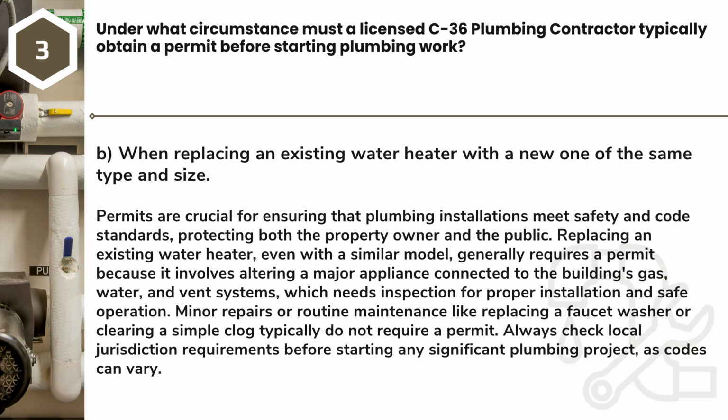Answer: B. When replacing an existing water heater with a new one of the same type and size. Permits are crucial for ensuring that plumbing installations meet safety and code standards, protecting both the property owner and the public. Replacing an existing water heater, even with a similar model, generally requires a permit because it involves altering a major appliance connected to the building's gas, water, and vent systems, which needs inspection for proper installation and safe operation.